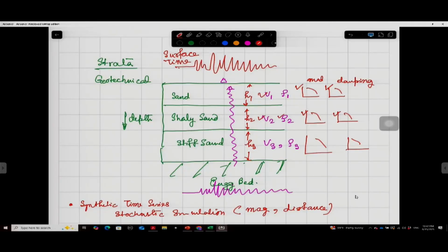The ground motion prediction equation has already been included when they generate the design spectrum, because they know this is the fault type at that particular place. So that geo database, whatever I'm talking about, already included some of the ground motion prediction equations. They have created this spectral hazard level using that data, so that is already included. You need not do the ground motion prediction equation. It is only required if you wish to generate the earthquake hazard map of a particular place. This earthquake hazard map is already generated, so you just extract the information and put it in the place.